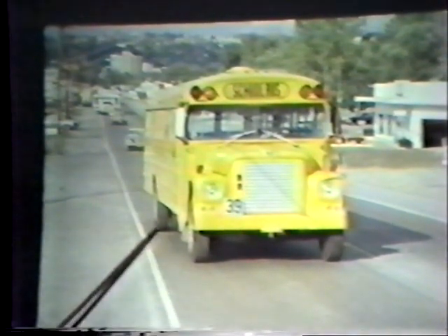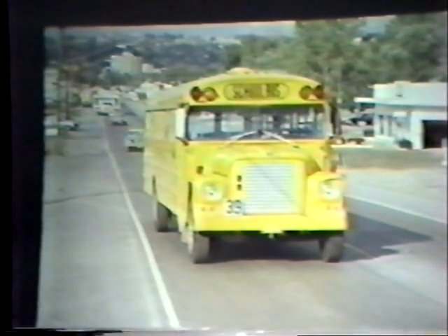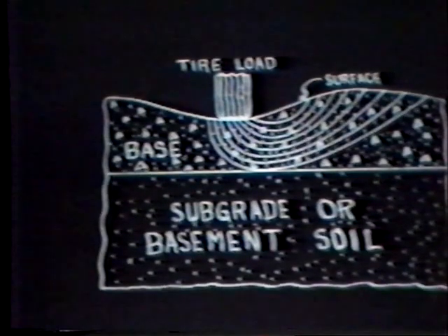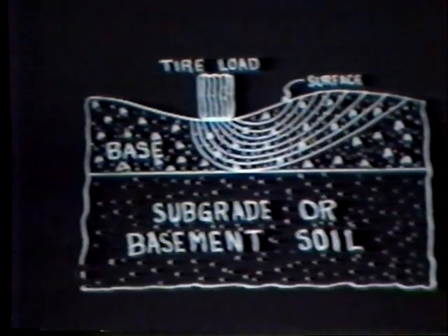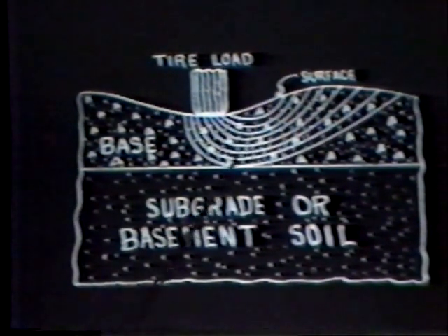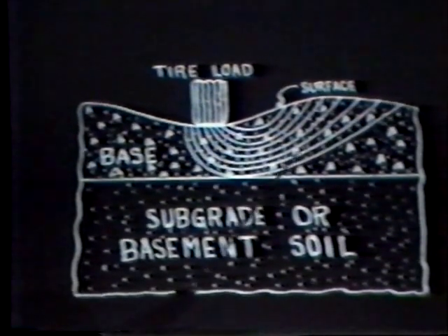Notice that all that load is distributed over just a couple of wheels, but on the concrete truck and so on, you've got a lot more wheels, so it does make a difference. The principle here is to try and provide a sufficiently, adequately strong base over the subgrade or basement soil so that the stress is dissipated.